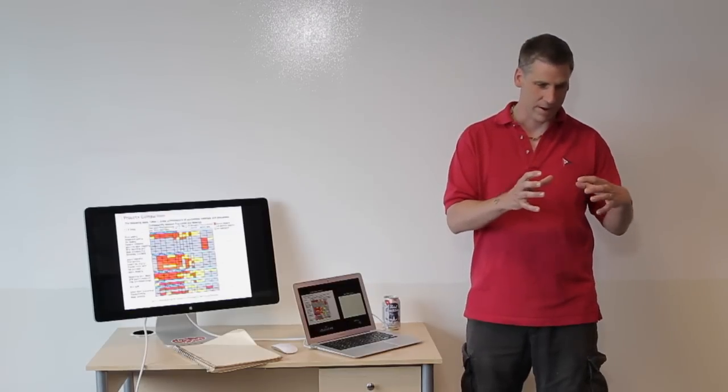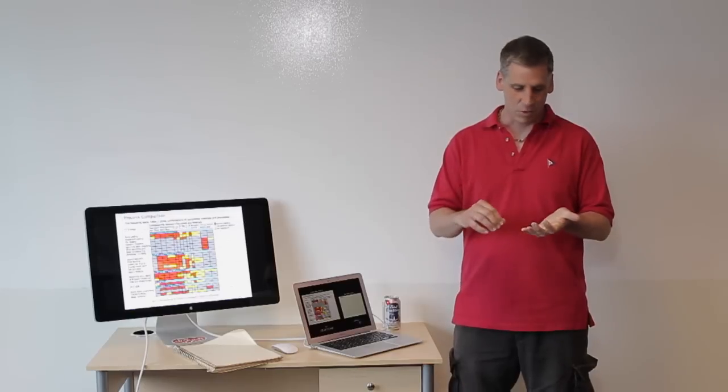Is 3D printing changing any, I mean, that chart doesn't even have it on there. That's right, this is old school. Yeah, 3D printing, I haven't seen change higher volume manufacturing, but it's something I'm really excited about. So it's done amazing things for going from the idea to the prototype. But the challenges with 3D printing, which I'm hoping, or let's say I'm optimistic, will be overcome in the next couple of years. I'm always an optimist. Is one, cycle time. So for injection molding, we usually do about a 30 to 45 minute cycle time per shot. Whereas if you think of 3D printing a thing, it's usually a couple hours for it to get done. So it's really too slow to get the volumes.